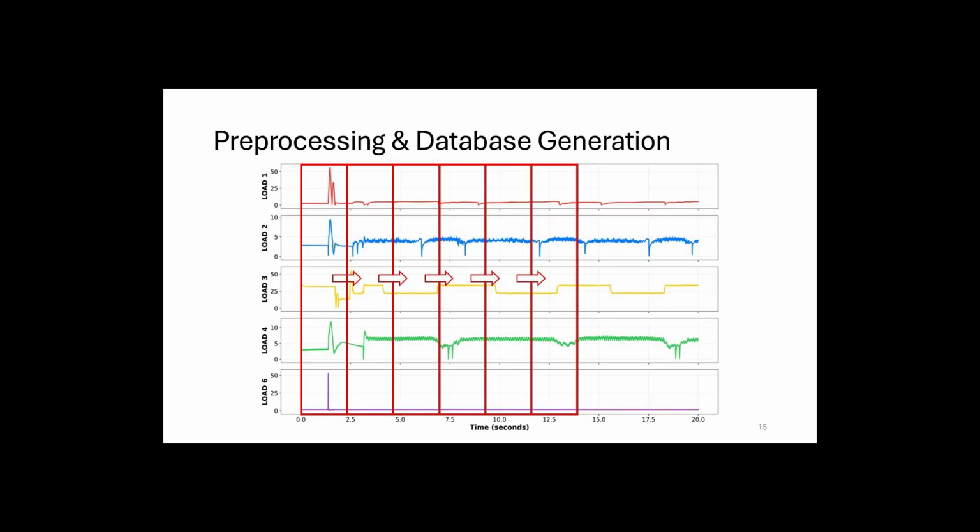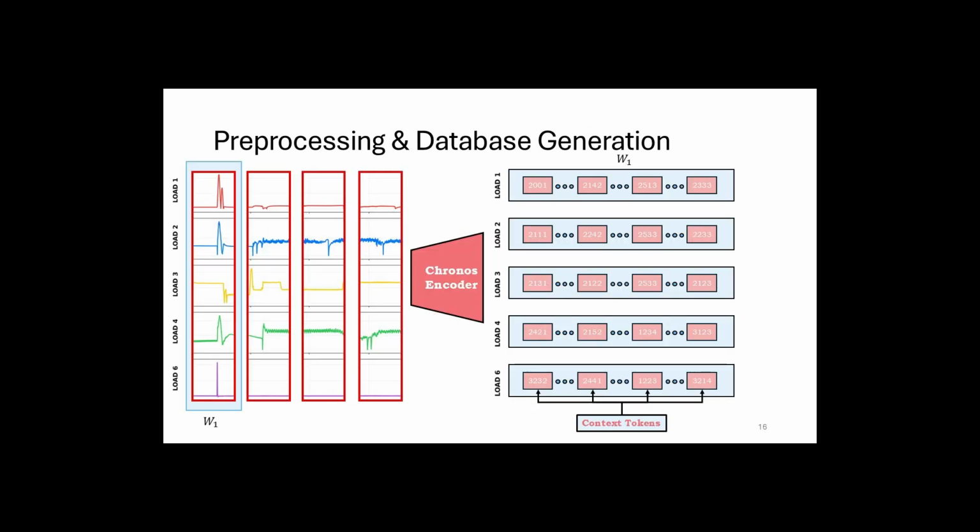So here we have some examples of the signals that were captured. We have load 1 to 6, skipping 5 because it's a 4-axis machine. So you have the X, the Y, the Z, and the A and spindle that were captured. And since we are working with 500 Hertz, that is a relatively large amount of data. And so we decided to downsample the data by 2 just to make sure that it's more manageable